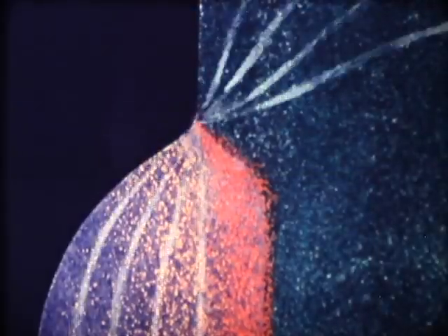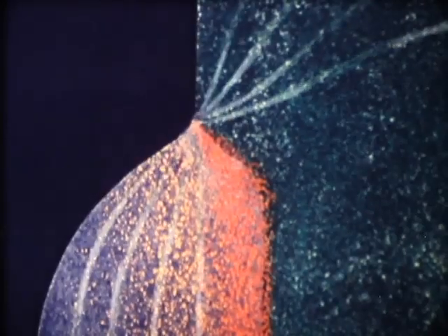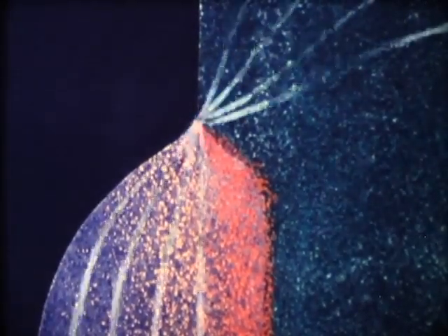In the equivalent circuit of a reverse bias diode, the series resistance can be neglected due to the high resistance presented by the junction. However, a leakage current flows over the edge of the junction, and this is represented by a resistance in parallel with the junction. The reverse characteristic of the junction is known, but we still have to determine the characteristic of the parallel resistance. As for any resistor, its characteristic is linear.